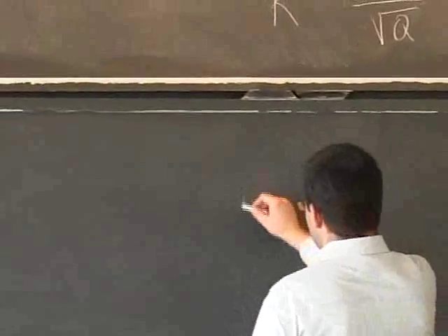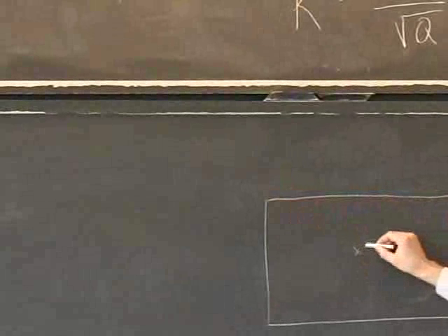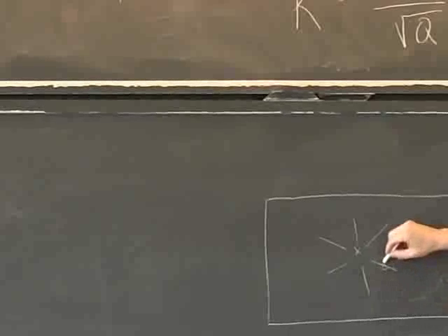So we have this situation here that it starts in the middle. And then when we see those lines going this way, this is what I'm referring to as crack propagation lines. How are you loading it? It's loaded in this direction. So it tells me that here the crack was going this way, here the crack was going this way, approximately. Because I essentially had two cracks that were growing, and that's where they met as they were coming together towards the outside of the sample.